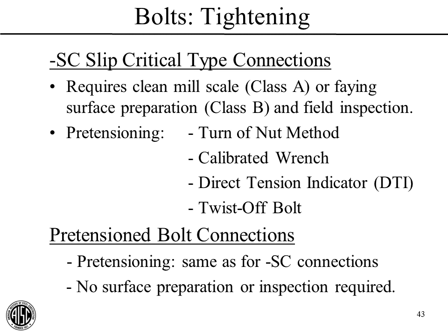For example, with the calibrated wrench method, I've read that the inspection requirements on those are such that it's pretty often. It's a lot more often than one would think. And then also for these twist-off bolts, they have to be taken care of in a particular manner on site to ensure that we have the right coefficient of friction there at the thread.